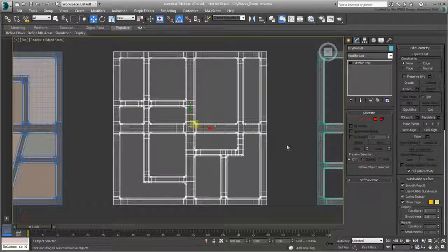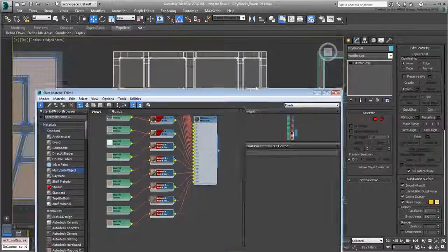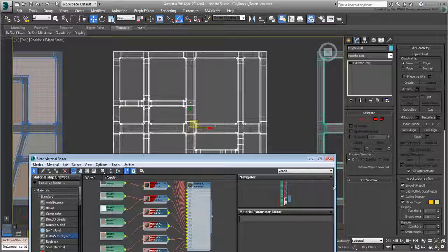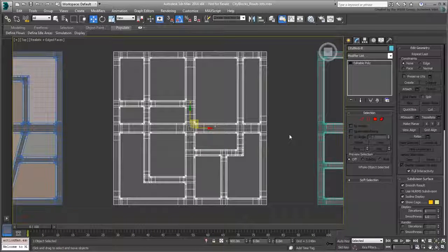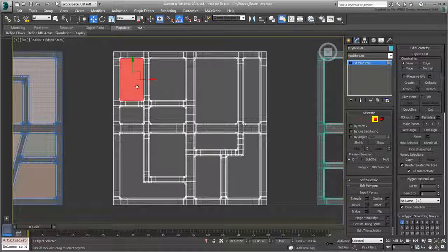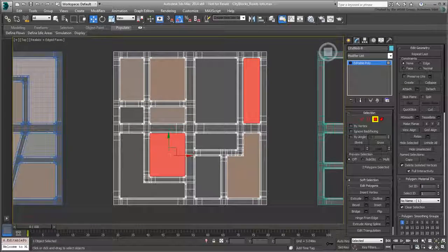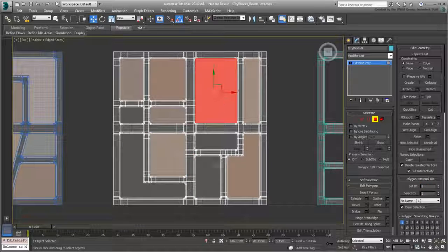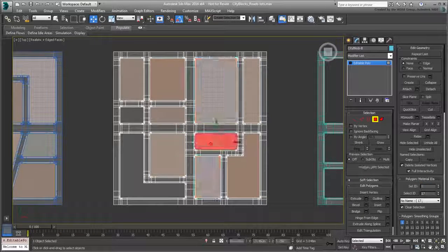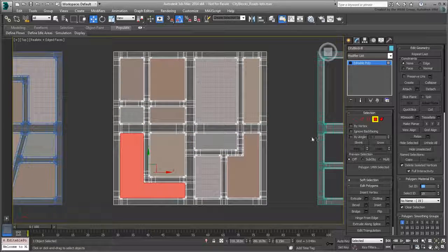Right-click to end the command, and apply the new consolidated material to the city block. From this point on, go into polygon mode and decide which lot goes on which texture by choosing IDs between 14 and 19. Exit polygon mode when done.